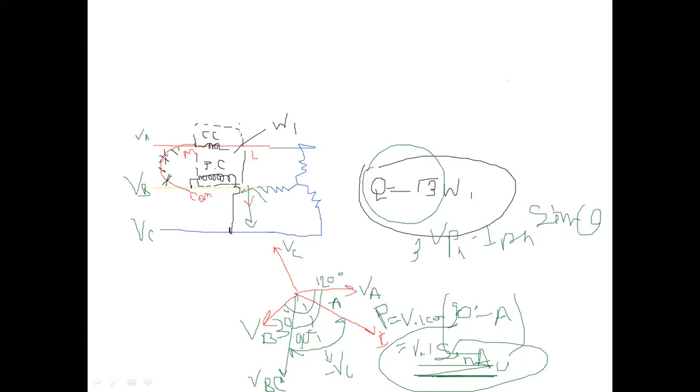M and com are not connected, they are separated. The com point is connected with B, and B point is connected with the other line. In this way, we can measure the reactive power. And if we apply a counter with the hour, then we can get the reactive var-hour energy.